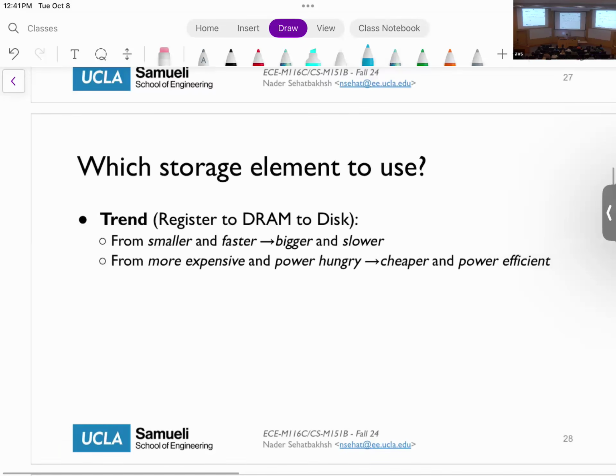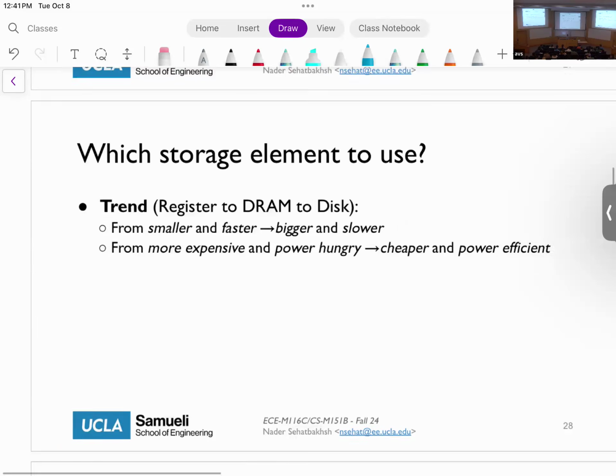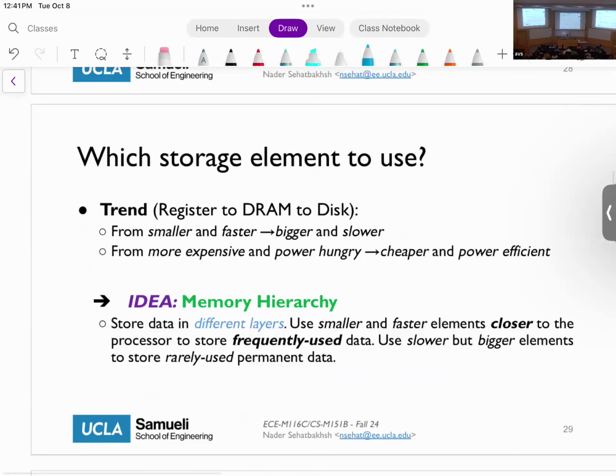Okay? So that's why I cannot have a really, really massive register file, because it consumes a lot of power that I cannot afford. And I already discussed why consuming a lot of power is a big challenge in designs. Right? And then, as I said, this is where the idea of memory hierarchy comes in.